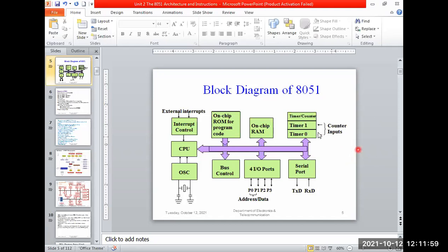So what is meaning of that? First, talk with the size of the 8051. What is the size of this 8051 microcontroller? Okay, so we know that it is an 8-bit microcontroller. 8051 belongs to the family of the MCS. Okay, so first feature will be what? 8-bit microprocessor. How to decide that? Depends upon the size of the ALU and the data bus. It indicates the size of the 8051.